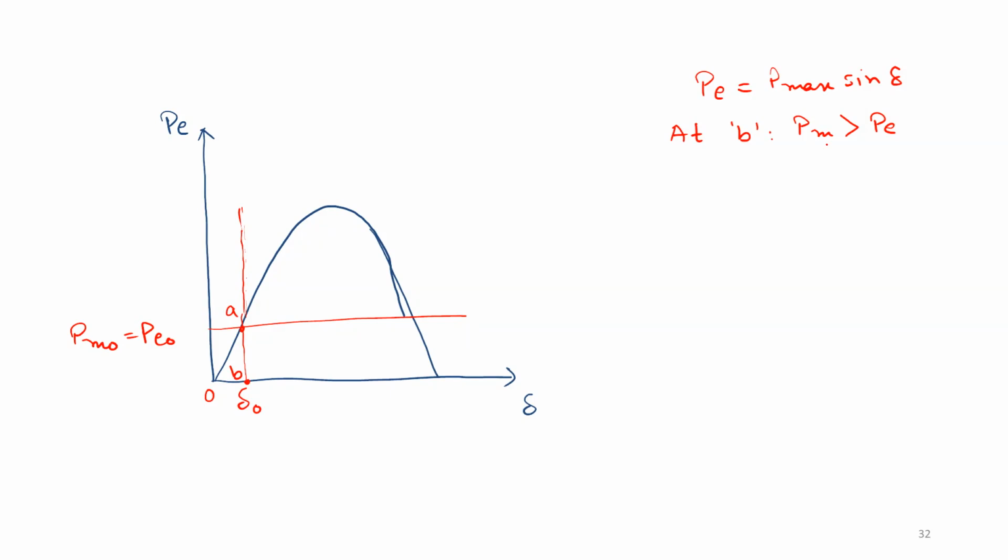No need to give the explanation because we already know these things. We have been discussing these things so far. Okay, so if your system accelerates, what happens to your delta or rotor angle? It increases. Assuming there was no initial energy stored, it started from 0 point. Then if there is pure acceleration, my pure acceleration will shift my rotor angle to the right.